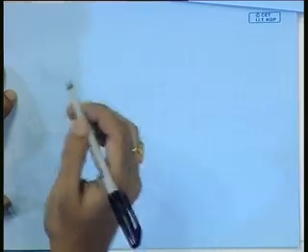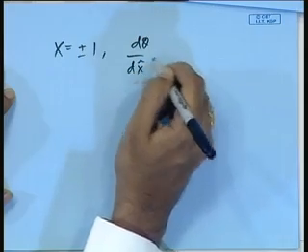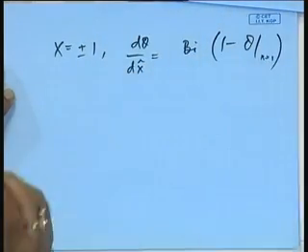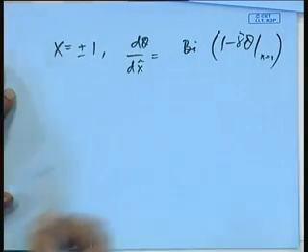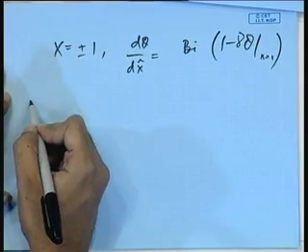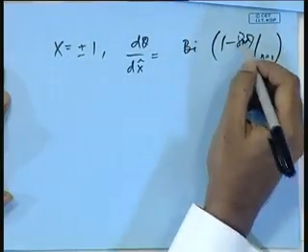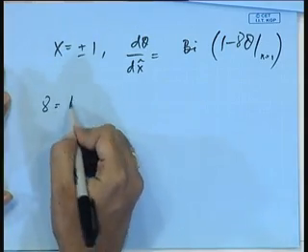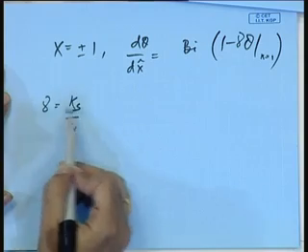Right. So, this boundary condition had been written without the reaction taken into consideration. So, you get del theta del x hat equals Biot number into 1 minus theta at x hat equals 1. If you have a reaction term, it does not make much of a difference. What happens is you just put a gamma out here, because the reaction term, if you remember, also has the external boundary condition at x equals 1. So, you can add your gamma over there, and gamma will have the ks over kf and so on. So, just a factor over there.